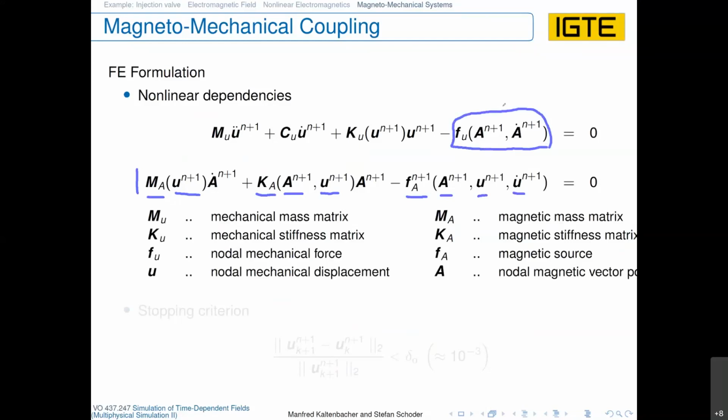Let's say it is according to the fact that we freeze now the magnetic field, and we can put this on the right hand side, and then clearly we can also include any nonlinearities due to large stresses or strains when you have to take this into account, and the mechanical stiffness matrix will depend on the displacement itself, but the mass matrix will be a linear matrix, and also the damping matrix when you include any damping.